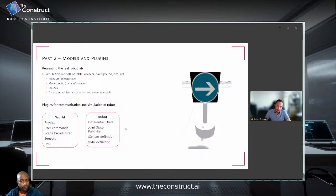Also, we need the joint state publisher. As you saw, the wheels of the real robot were also moving in the visualization of RViz. And this is because we always have this joint state publisher, which is publishing the joint information of the robot. So whenever something is moving, for example, the wheel, the joint is also, of course, rotating, and this information has to be provided to the system, to ROS. And therefore, we need this joint state publisher in our simulated robot to also have that information outside of the simulation.